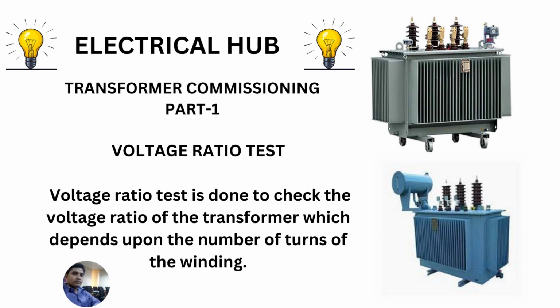Now, the voltage ratio test. The voltage ratio test is done to check the voltage ratio of the transformer, which depends upon the number of turns of the winding. For example, you are using a transformer 11 kV to 415 volt, or someone is using a transformer 13.8 to 440, or 22 kV to 440, or 132 kV to 11 kV.